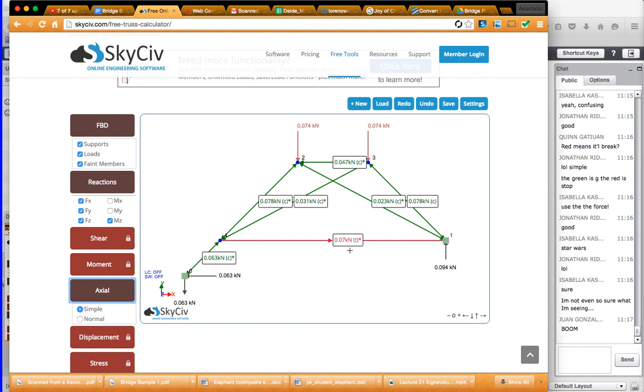So that's a good way for us to see exactly where this thing will break and where it will survive. It will usually survive over here because the pieces of wood are being pushed together. It's not like the glue has to do anything at that point. You know what I mean? If you glue two pieces together and then push them together, that's not going to break it. If you glue two pieces together and you pull them apart, like the red stuff, that's going to break it. Does that make sense?